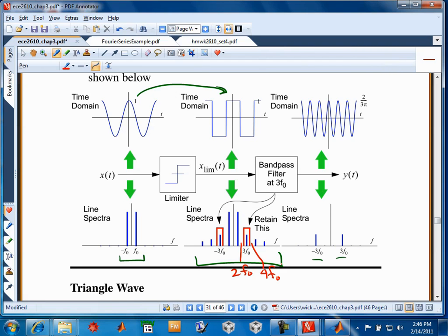And then it comes down to, can we always make a limiting circuit, or can we always guarantee that a clock waveform is always 50% duty cycle? There's just some other considerations that come up in there. In the electronics that I passed around, it relies on how well matched those two diodes are, whether or not it produces a nice symmetrical square wave.